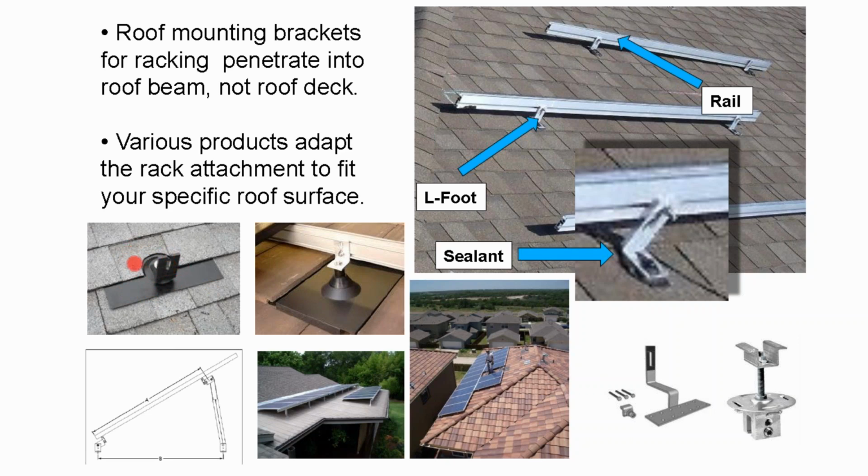And this is an arduous process. You've got to get a pry bar and pry up the nails underneath the shingles, and it's not a perfect process either, because the shingle companies don't want you to do this. Some will allow it, some won't. It's good to check. Most don't check.